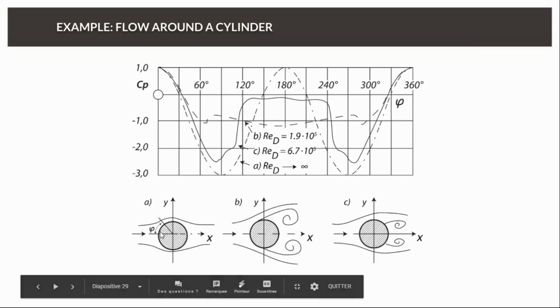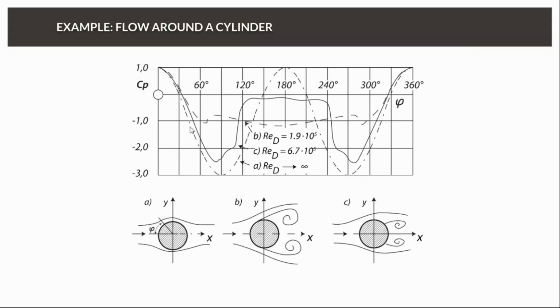So given curvature from 0 to 90, it is a decreasing pressure. Even if it's positive at the start, it's still decreasing all the time. And then once we pass the maximum y, the curvature is such that the pressure will recompress, re-rise, coming back to the trailing edge where we'll reach 1 again.